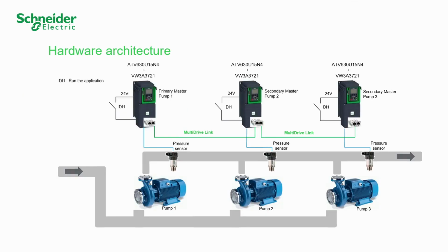Here is the hardware diagram of our test bench. The link between VW3A3721 is dedicated to the multi-drive link for data exchange in high-level priority. If you need to monitor the drives, connect the supervision system on the embedded Ethernet connector on Altivar Process.